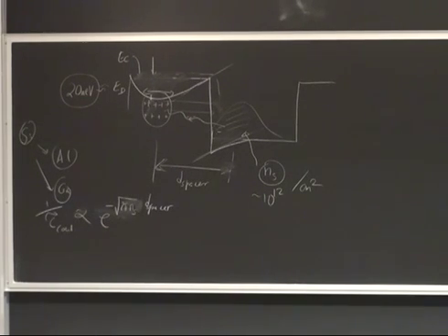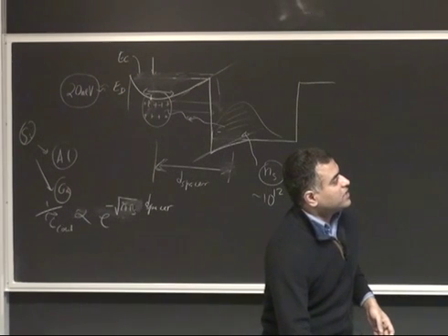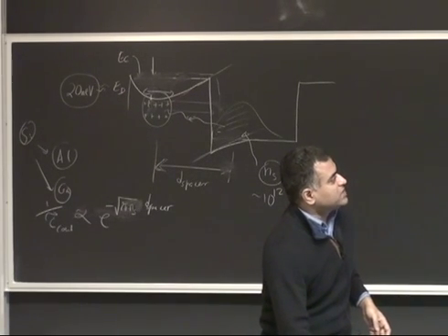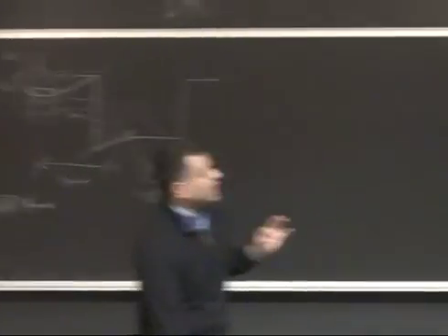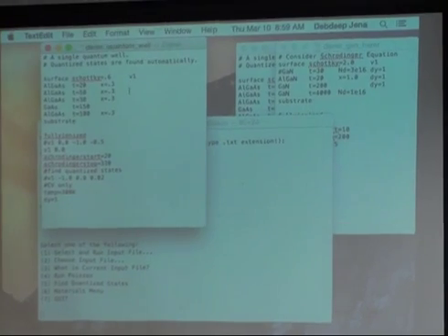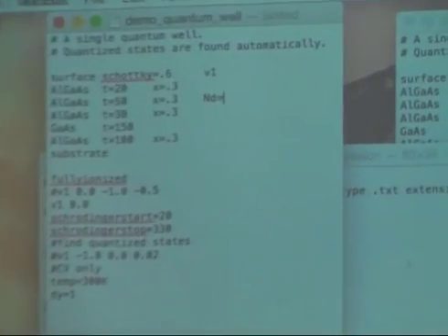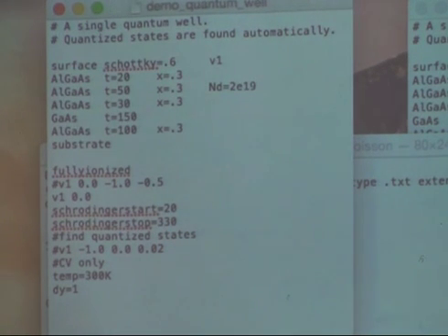This is one of the designs, not necessarily the only one, not necessarily the best one either, but I've broken it up because I want to put dopants in this middle layer, over that 5 nanometer or 50 angstrom of 30%. I'm going to put a dopant of very high, let's say, 2E19 per centimeter cube, and then ask how does this change the band diagram? And basically it's going to just do this. That's all.